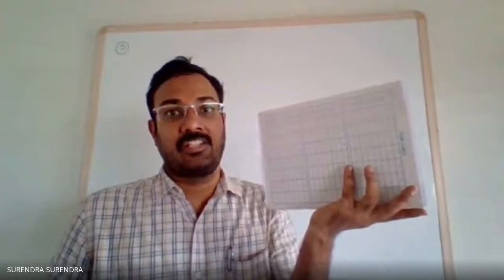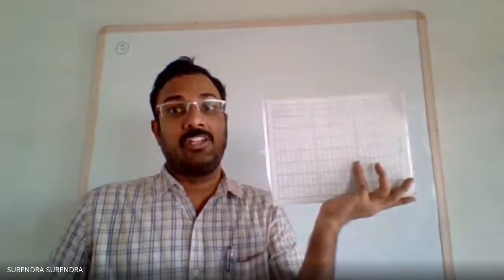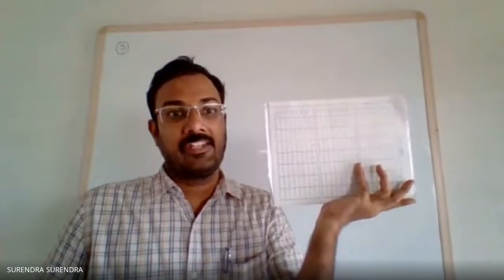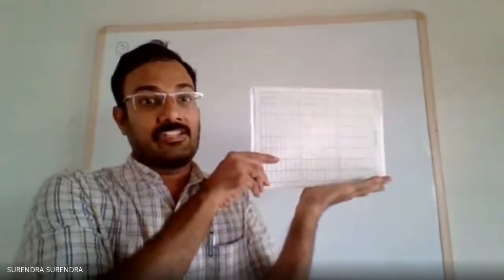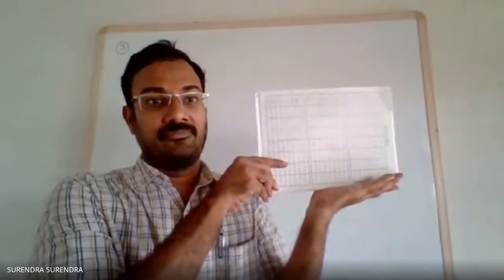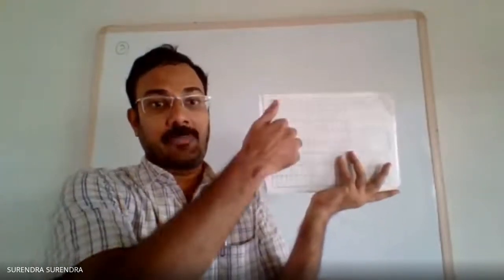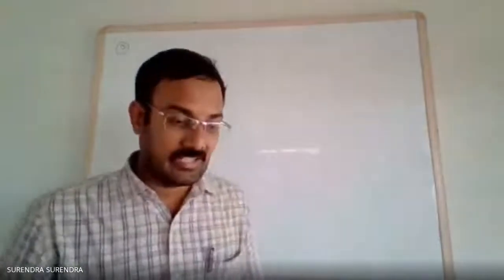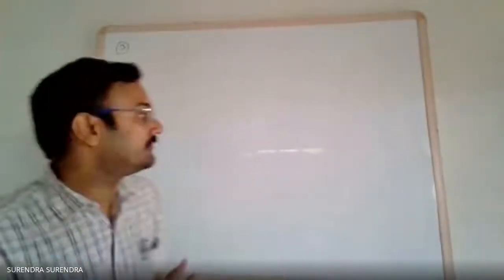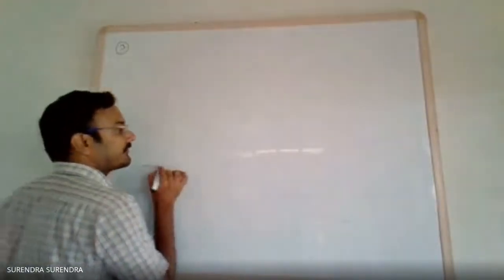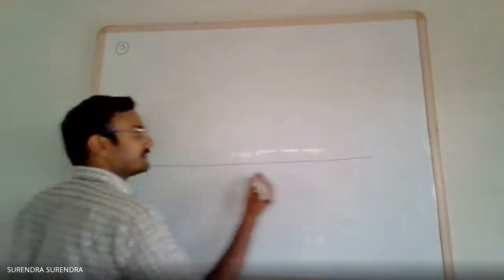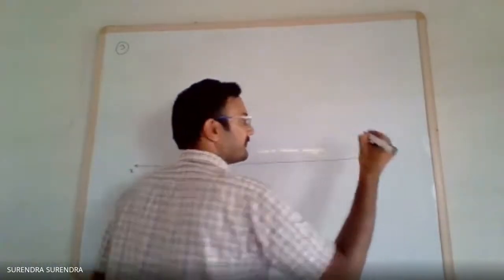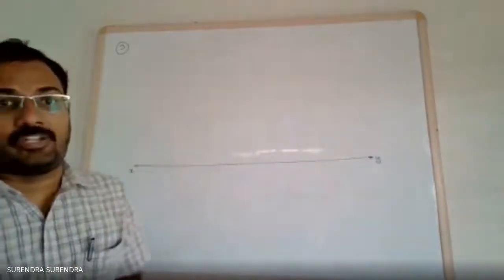As the surface is inclined to VP, make it parallel to VP. Make it parallel to VP. Now, we can see the true shape in front view, and top view as a line. So we may start the problem with front view as a hexagon. Draw XY line. Draw the front view as a hexagon.